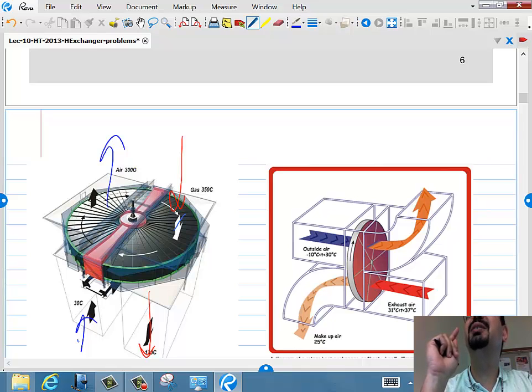The main mechanism is, right, the plate gets soaked in the hot fluid for a long time, so this thing is rotating very slowly. So it gets soaked, becomes really hot, not red hot, but really hot, and then it passes to the other side, where it gets cooled by the fluid. Right? So that's the air preheater they have to heat the air before it goes to the furnace.